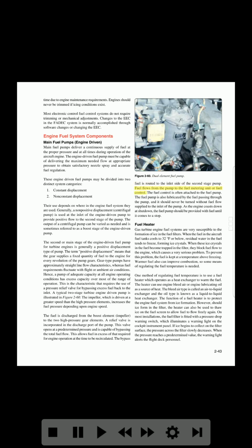Fuel flows from the pump to the fuel metering unit or fuel control. The fuel control is often attached to the fuel pump. The fuel pump is also lubricated by the fuel passing through the pump, and it should never be turned without fuel flow supplied to the inlet of the pump. As the engine coasts down at shutdown, the fuel pump should be provided with fuel until it comes to a